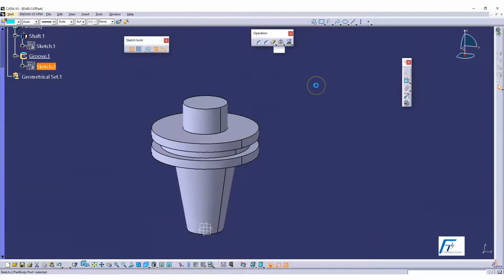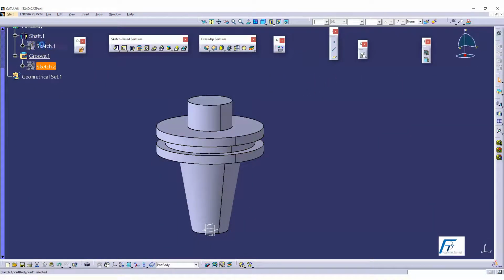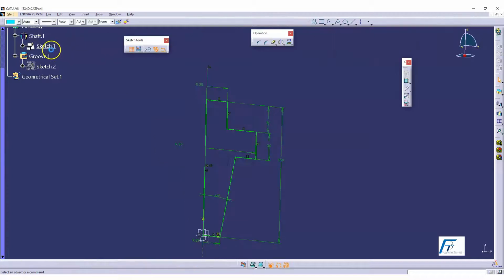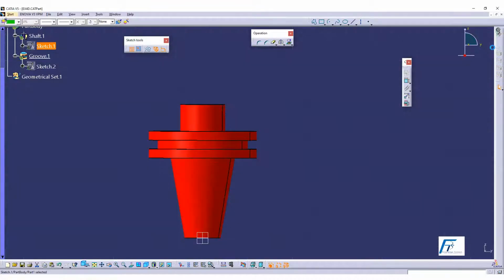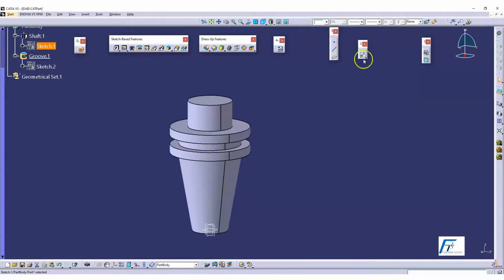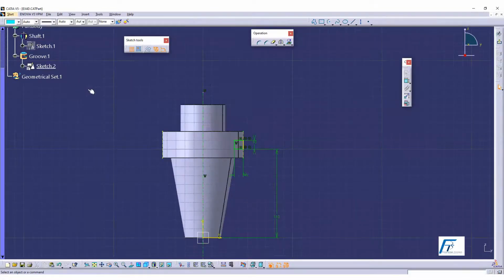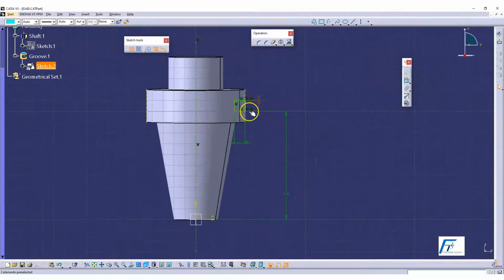Exit this one. Whatever dimensions you keep changing on this groove, say for example, I just changed here from 60 to 45. Earlier it was a challenge, right? Now always the groove will be following, and this groove will not change its cross section as well. See this? It follows. So this is the purpose of the best design practice. The design is best when it is modifiable and doesn't break when you make changes. And that's the process which you need to understand.